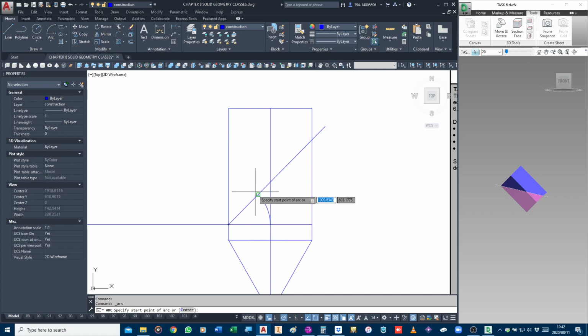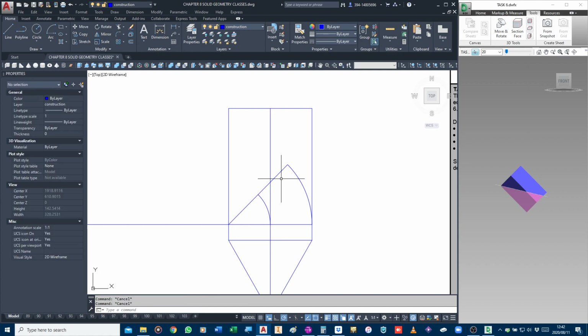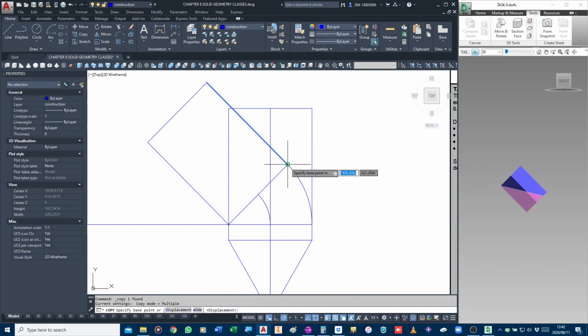The same for the next point. That is where I put my pencil, the steel tip, and that. So we can now be comfortable that that is our base. Okay, from there, because this is 45, I now project this line at 45 degrees at 74. This distance is the base edge, 54. Okay, and I can just copy that, which you obviously can't do on your drawing.